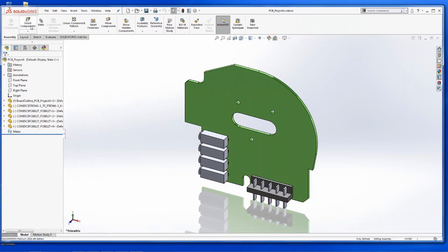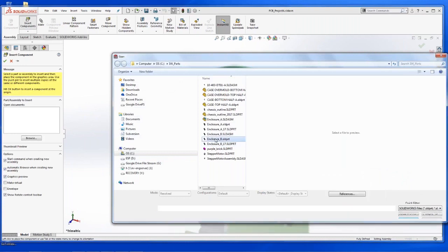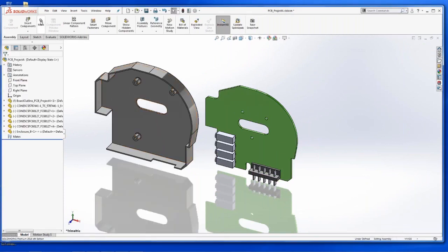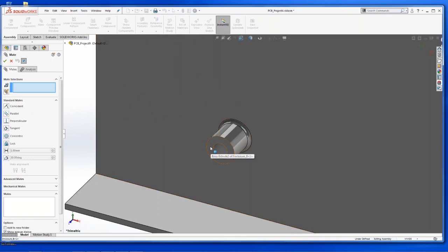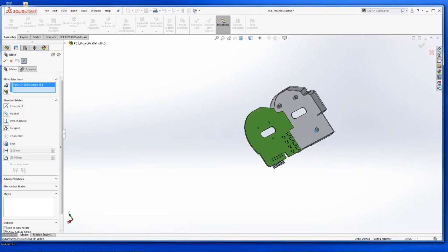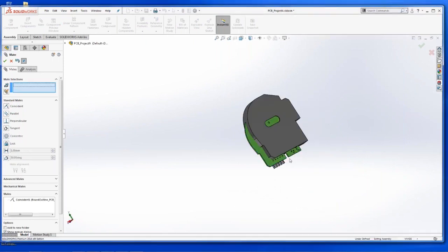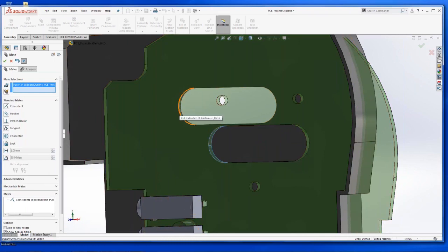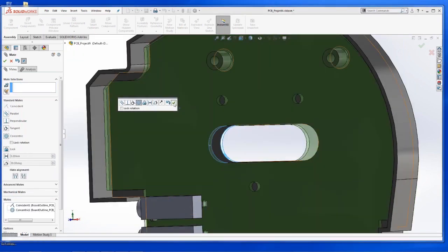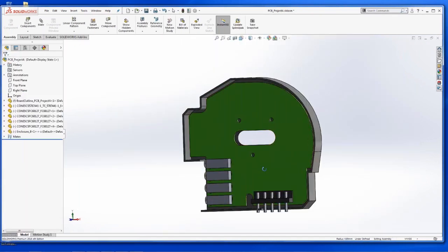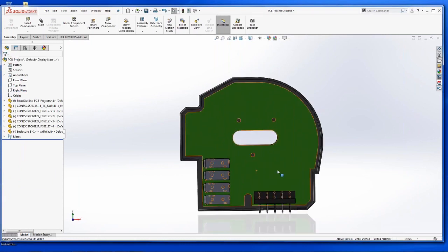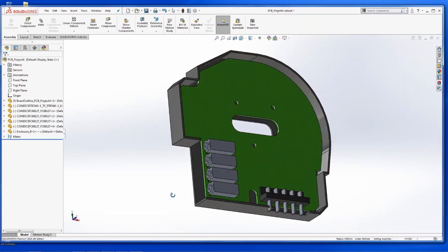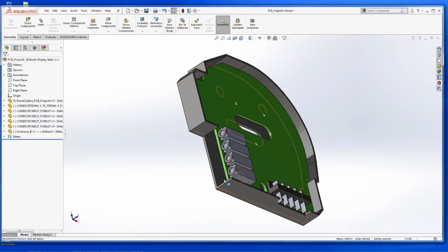Okay, so now I'm going to add my new chassis, and we'll match that up and do some checking for interference. Okay, quickly again, we're going to take the surface of our standoff. Okay, and that needs to be referenced on the back of the PCB. And now what we can do is we can reference the slot faces together to ensure that we have that relationship correct. All right. Again, simple 4 clicks in SolidWorks. I've now got that new board into the updated chassis, and now I've provided that board to chassis clearance, and I've added a slot for the power connectors and my audio connectors.